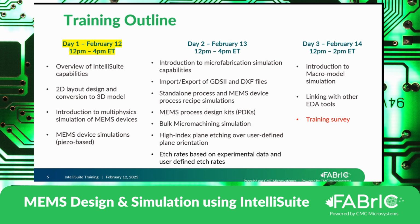If you are in the stage of optimizing the design, then this approach is good. But if you have still not figured out the simulation settings that are required for the device that you are trying to do, then don't get into parametric simulation now.